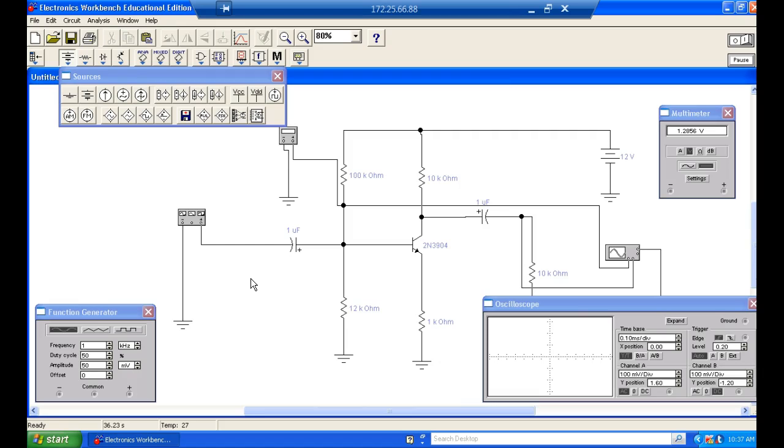What we do is we start off coming in with a high input impedance, right? Because we don't want to load the signal source. By the time we get to the end of the amplifier, we want a low impedance amplifier because we're trying to drive a lot of current, a lot of load, right? Well, what we do is we go through several stages.